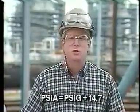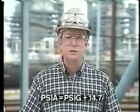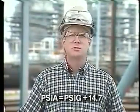Often it's important to use and consider absolute pressures on the job. To get these absolute numbers, you'll calculate them from a gauge pressure. PSIA, pounds per square inch absolute, represents the gauge pressure plus 14.7. This gives the total pressure on the fluid.